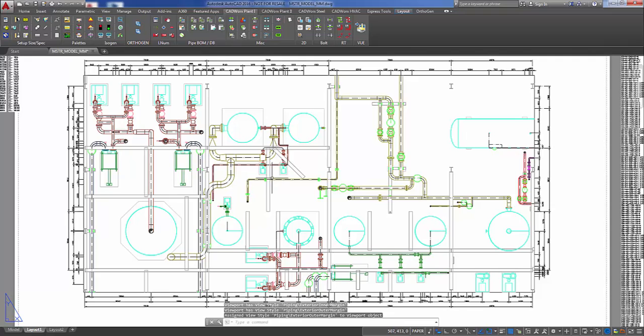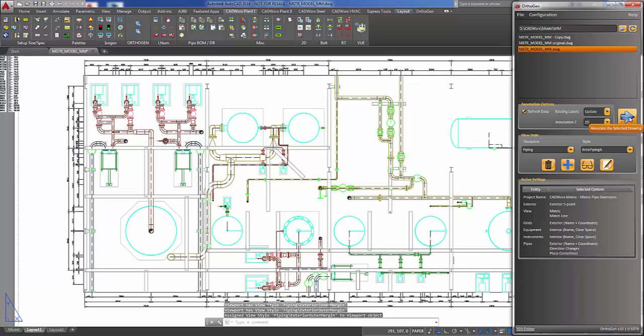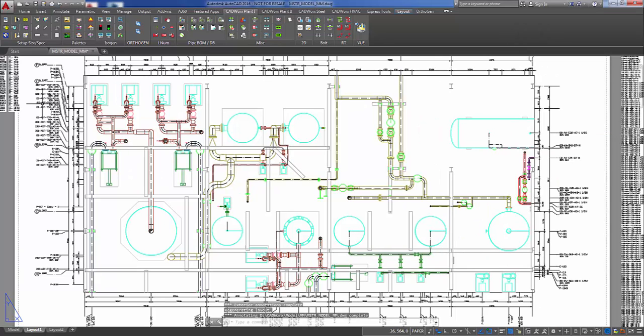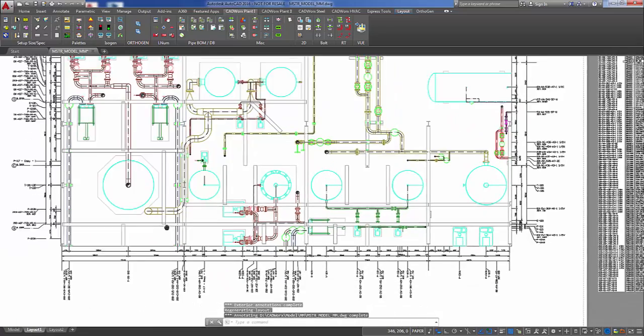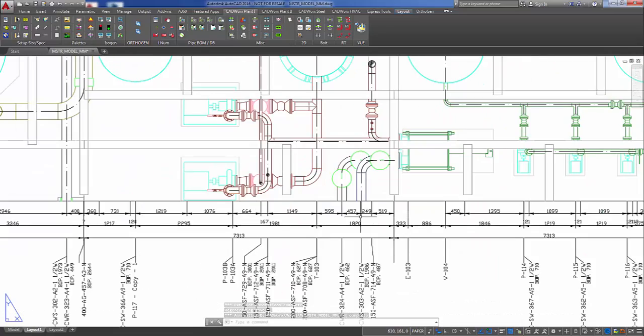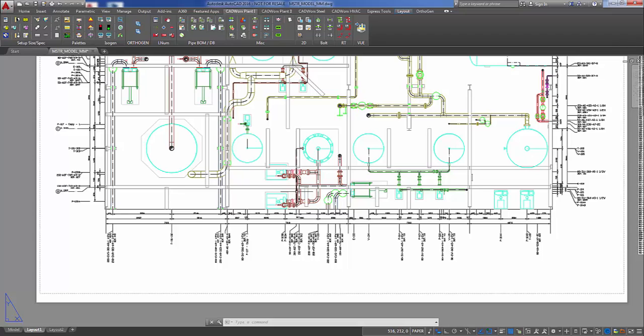Now we've got two styles assigned to this viewport, and if I update it, you should see the exterior inner margin, which is the dimensioning, and then exterior outer margin, where it adds the name labels outside of the dimensions. So we've added, permanently assigned to the viewport, the names of the view styles, multiple styles. You control the order that they're executed and so forth.